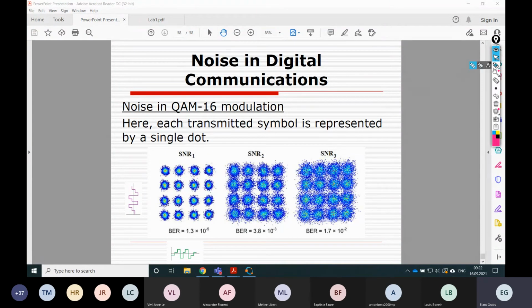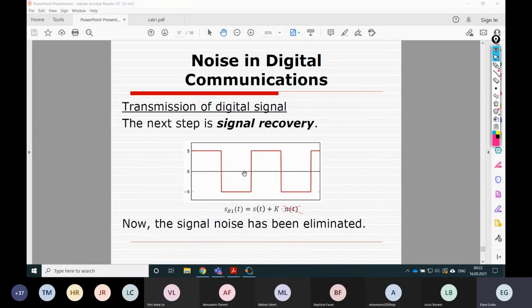So we'll talk also about more advanced modulation types, one of them called QAM16, quadrature amplitude modulation. Basically, this QAM16 has not 2, but 16 different signals. Here we had only 2 signals, 1 and 0. For QAM16, we have 16 combinations of 1s and 0s, starting with 4 zeros, ending with 4 1s. And each of these symbols has different amplitude